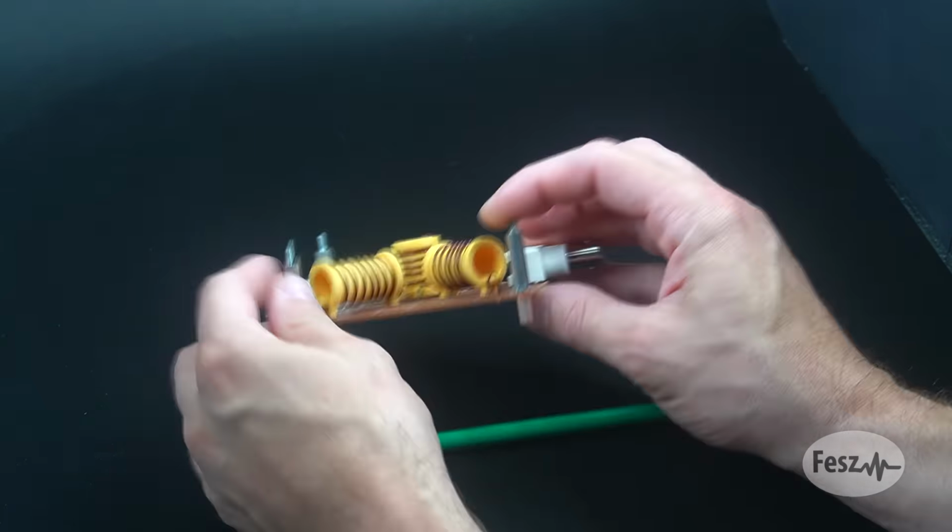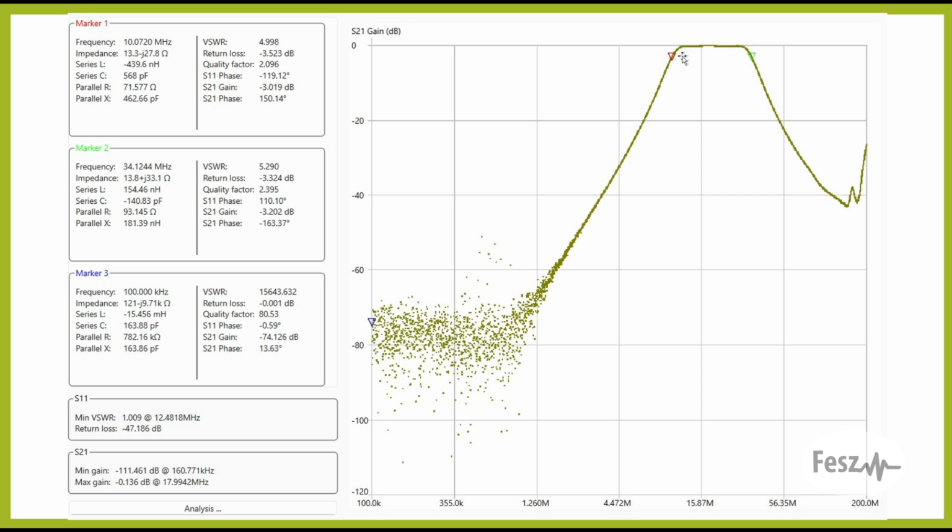First, the general filter response. It's bandpass behavior. So we can check the 2 corner frequencies, so where the gain passes through -3 decibels, and these occur at around 10 MHz and 34 MHz. So this is more or less in line with what the filter calculator tool predicted.